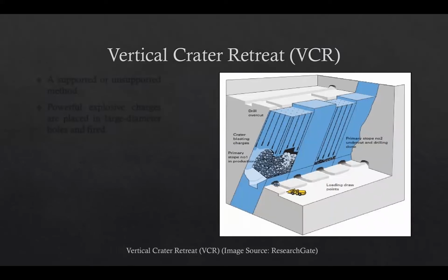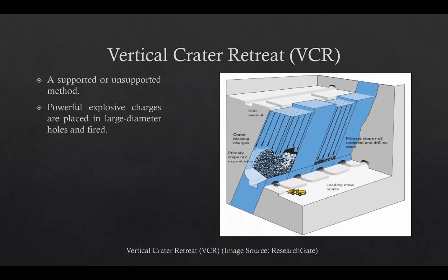Next one is vertical crater retreat. Crater retreat can be either a supported or unsupported method based on the crater blasting technique in which powerful explosive charges are placed in large diameter holes and fired. We have these long and large diameter holes, and then we place the explosive in it.